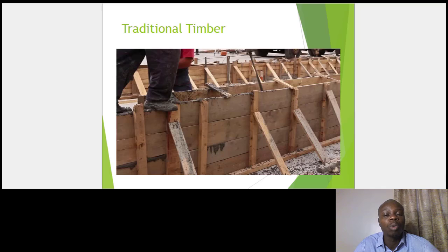We said that formwork is used especially to make sure that the wet concrete, in that green form, can have the shape, because concrete is a structural element, and therefore for it to have the intended purpose, it must conform to certain dimensions and attain certain strength requirements.